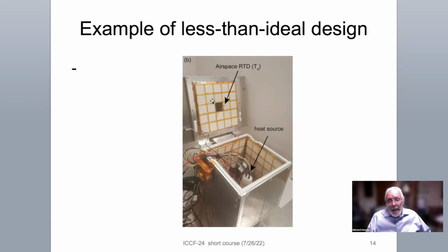You can't see that they did this, but they pass the water into and out of the top. It's better to have it pass into and out of the bottom, so that the water lines to the constant temperature bath are as short as possible, once again, to reduce the effect of room temperature.